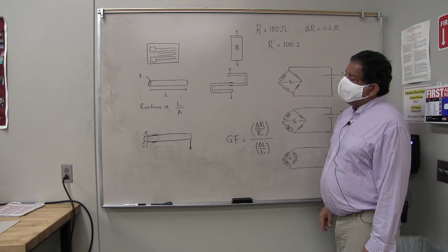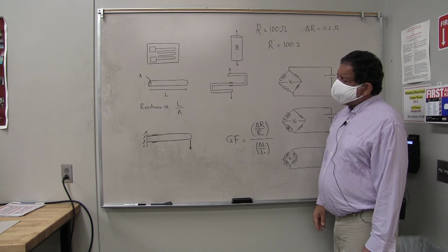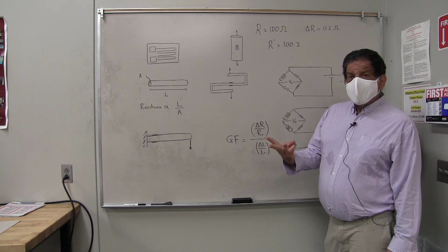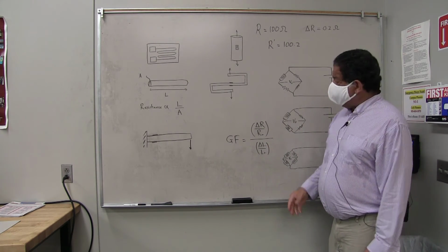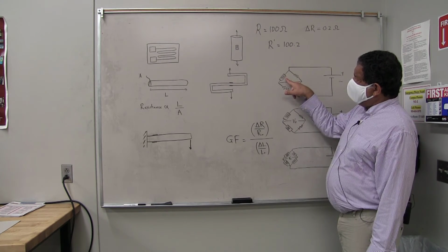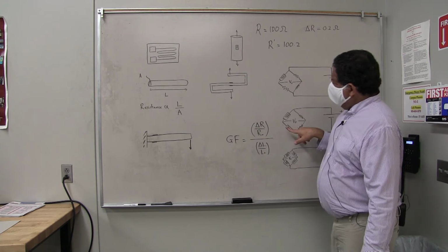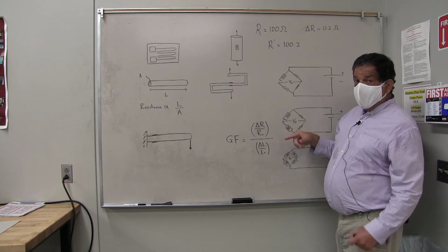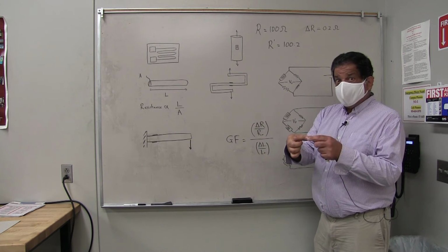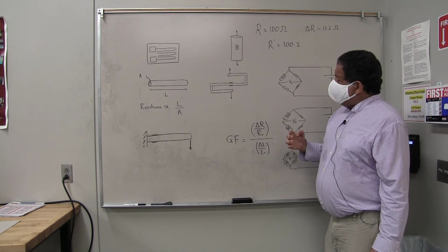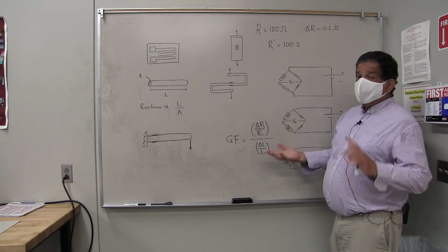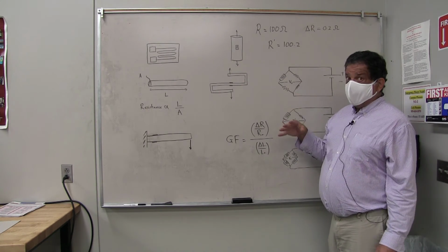So that's another cool advantage of the half-bridge setup, is it compensates or rejects the modes of deformation that you're not interested in. Now, the third setup that we're going to be using in this experiment, where we have one active gauge actually attached to the object, and then the other active gauge is attached just to a block of steel, has some advantages and disadvantages of both setups.